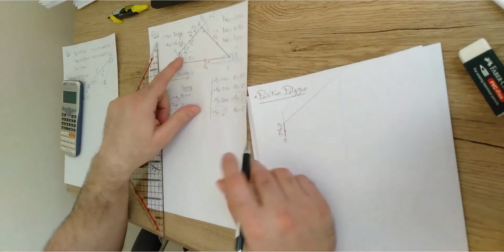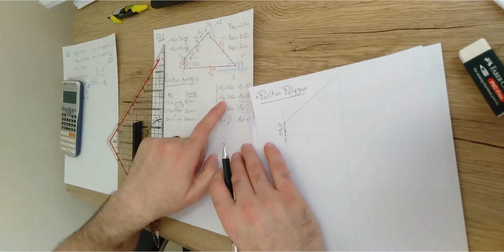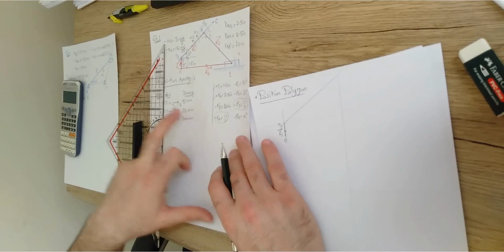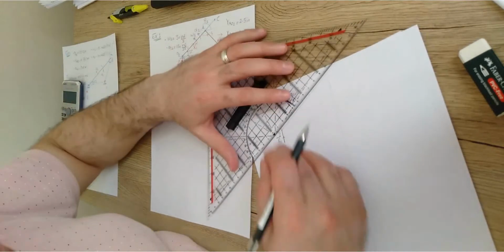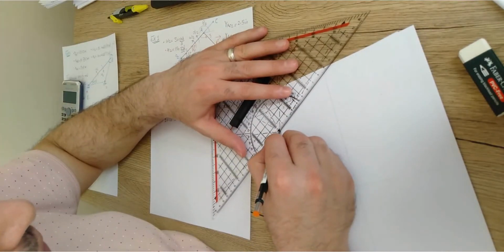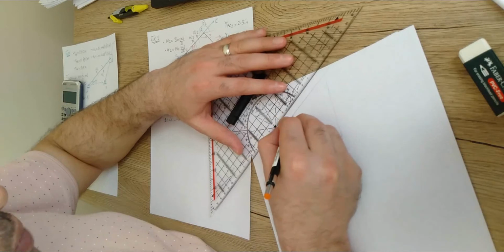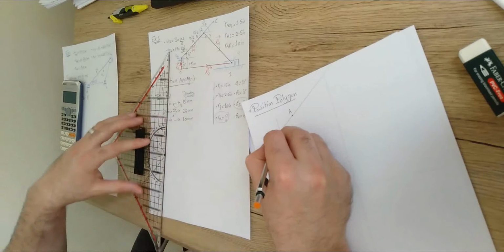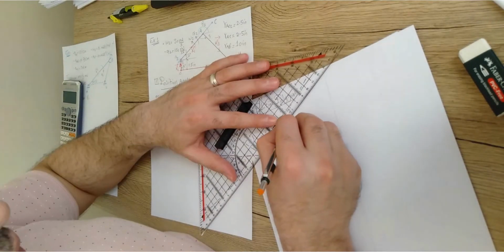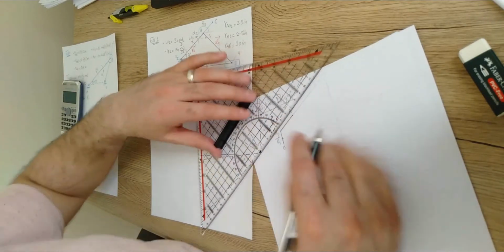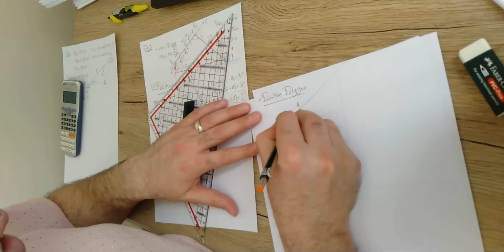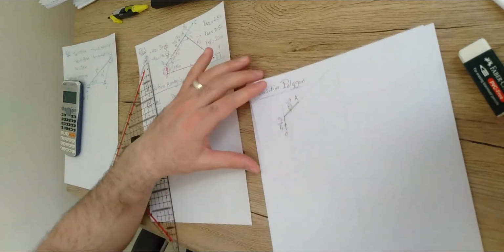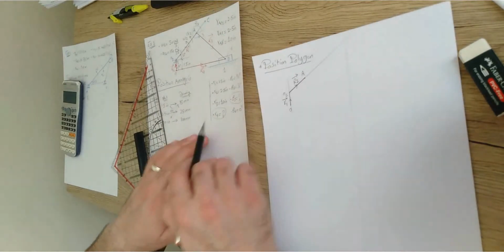Over this line, you're gonna measure the length of O2A, which is R2. R2 is already 2.5 inches, which, according to the scale, I'm gonna draw as 25 millimeters. So what does it mean? It means that I'm gonna measure here 25 millimeters as already given here, and mark a point. This point definitely will be point A. So we had point O2, now we got point A for this length, and this should be the R2 vector, as we already defined this vector up there. Make sense? Once we defined R1 and R2, which are fully defined, we're gonna move to R3.